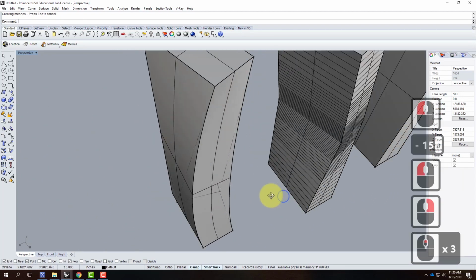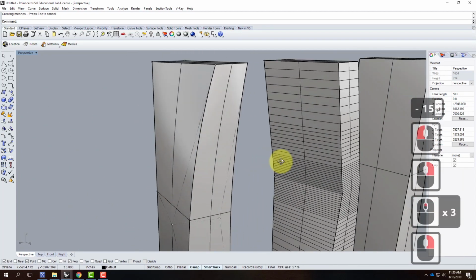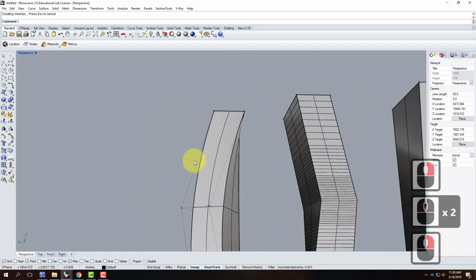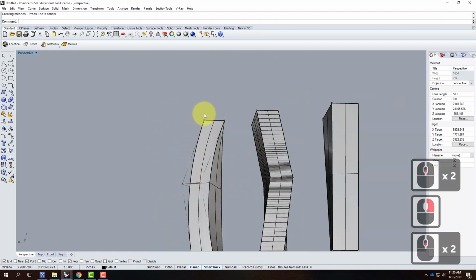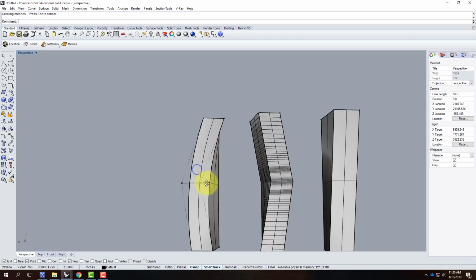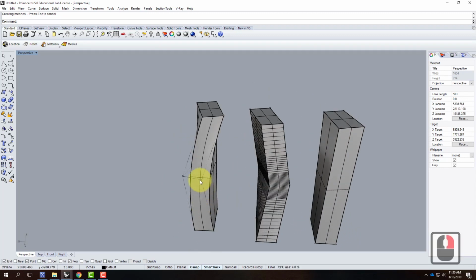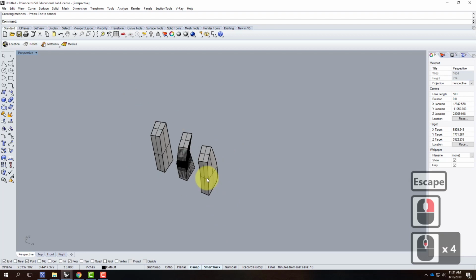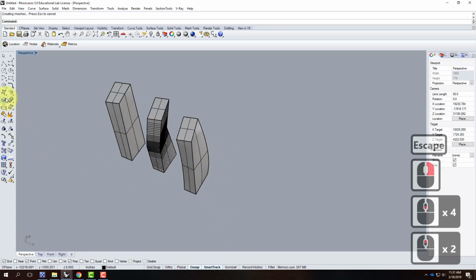Like that. And you can see that it's starting to twist that building. These surfaces, because it's only a 2-dimensional curve, it's curving in this direction, but not in this direction. So it's still a developable ruled surface. So I could still unroll this object, because the curvature is happening here and not in between, like that. It is possible in a cage edit to get 3-dimensional curvature